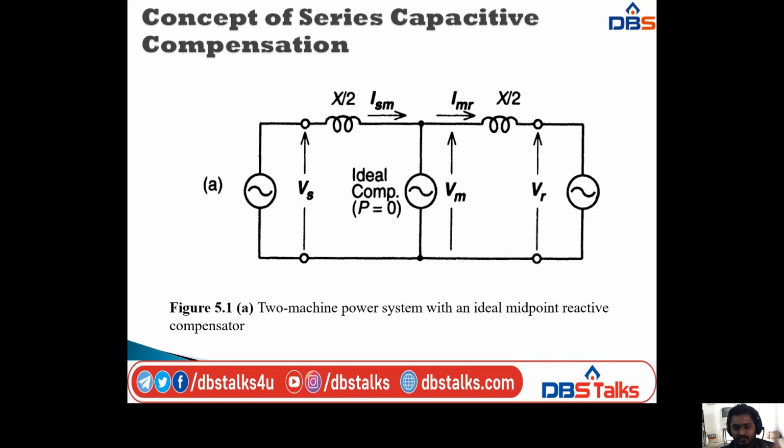So here we have two machines, one at the sending end and another at the receiving end, that is Vs and Vr. It consists of the voltage Vs on the sending end and Vr on the receiving end. At the midpoint of the system we have an ideal compensator. In this one we have the power equal to 0 and we have the midpoint voltage Vm, and on both sides we have the reactance X by 2 and X by 2, and we have the currents ISM, the sending end to midpoint current, and IMR, the midpoint to receiving end current, and X by 2 is the value of the reactance we are using.